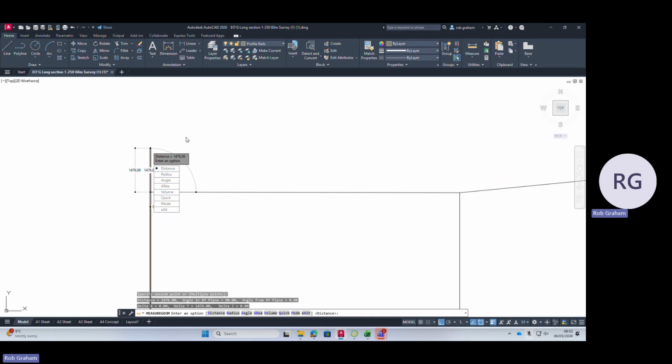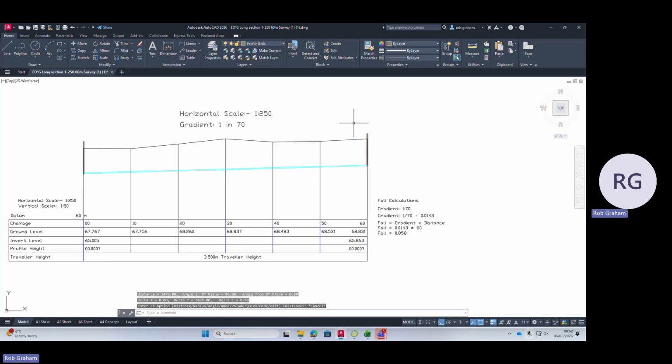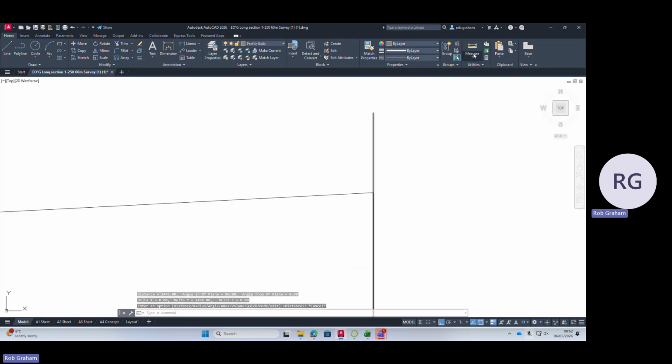So we're getting 1476 here. If we divide that by 2, that gives us 738 mil above ground level. So it's above the 0.5 threshold and within the 2 meter threshold. That one's okay. And again, we check the distance here, 1064, which is just 532 mil. So it just about meets that threshold. As I say, it's better to have to bend down to use these than to jump up.